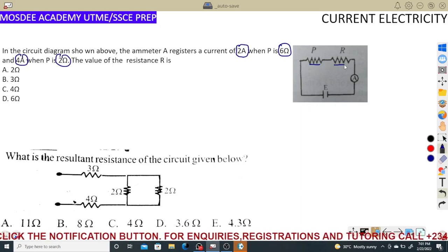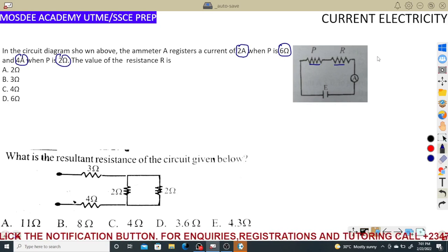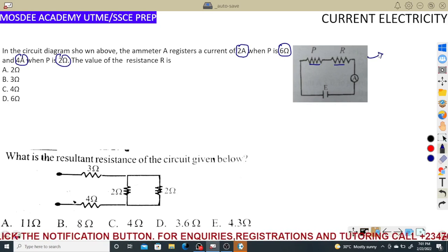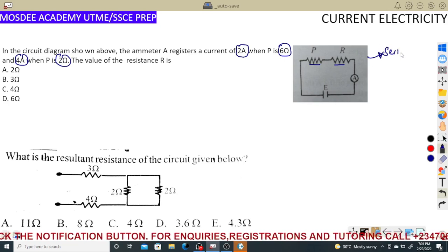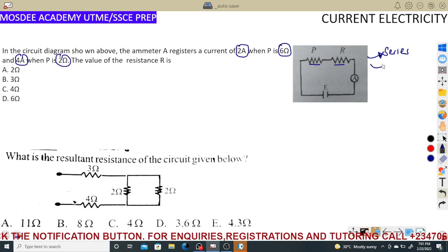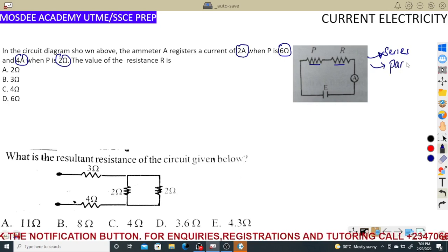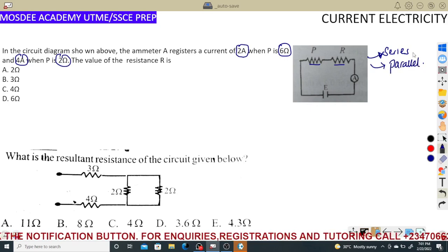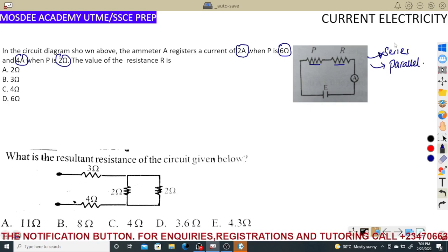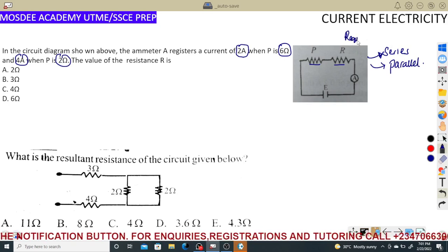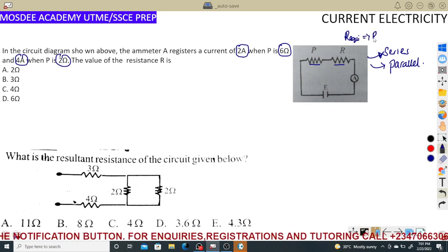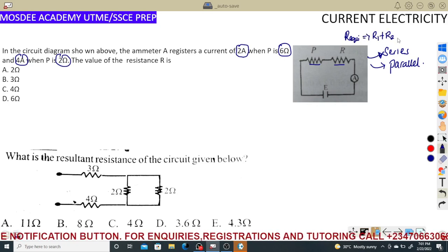Arrangement. We've talked about arrangement for capacitors. The same thing for resistors. Resistors can also be arranged in series and also in parallel. Now, what you just need to keep in mind is just the inverse of what we've done for capacitors. So, equivalent resistance for series, R equivalent, is equal to R1 plus R2 till infinity.